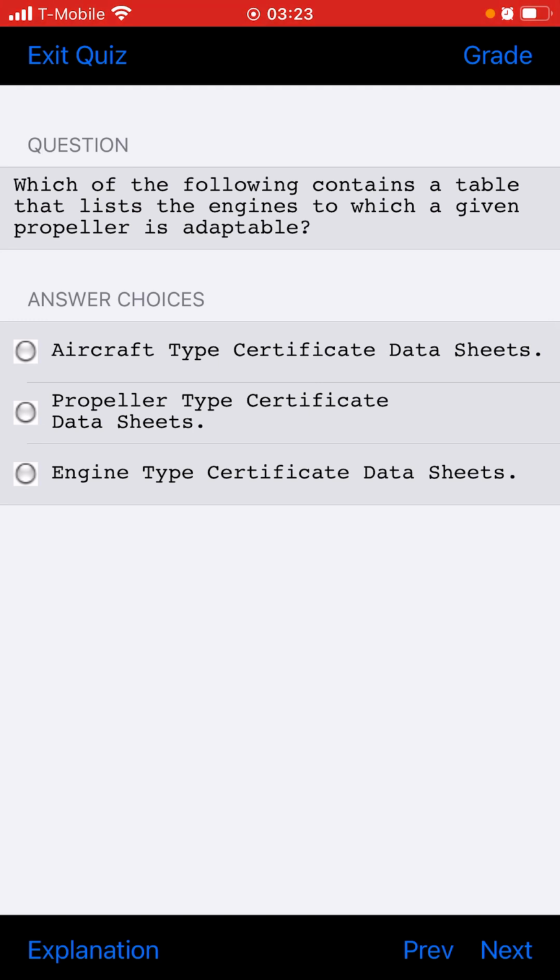The color of the insulation shows the size of the terminal fit. So statement 2, which said electrical wires smaller than 10 gauge use uninsulated terminals, is not true. They use insulated terminals. Electrical wires larger than 10 gauge use uninsulated terminals. That is true.